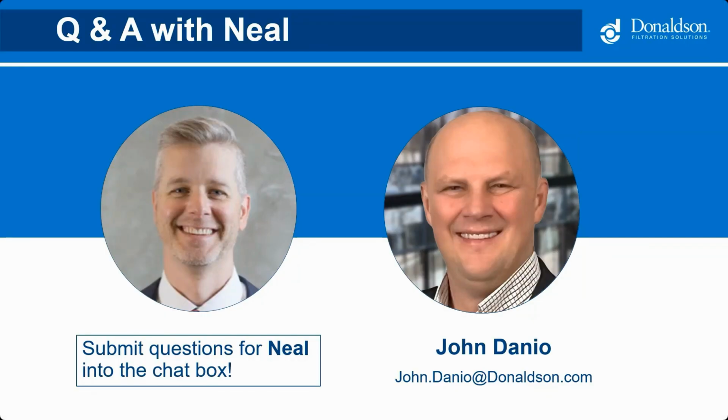Thank you. So your next question, this is in the ductwork section. They're asking about conveying velocity and why is it that 4,000 feet per minute is the minimum if the dust is combustible? That is a great question for NFPA. The answer that I have is because NFPA says so. But I think it has to do with the likelihood of dust being able to fall out and settle out. 4,000 feet per minute is pretty low, right? It would have to be an extremely heavy dust to not be conveyed properly at 4,000 feet per minute.